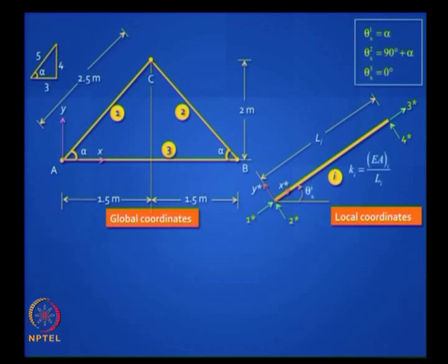Okay, let us start numbering the global coordinates. Where do you start? C, you are right, 1, 2, 3, those are my active coordinates. What is restraint? How many are restrained? 3. 3, simply supported. So 4, 5 and 6. You can choose any one, the sequence is not important. Is it clear? Usually after 3 you should put 4 near the 3, so I put it at B.